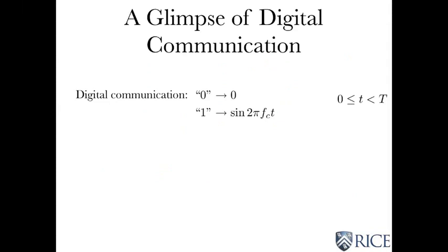Let's explore the frequency domain in another case of digital communications. I want to tell you how digital communication works. We're going to explore this in much more detail later. So here's the idea. I want to send a bit, either a 0 or 1, to the sink, to the receiver. And one way of doing it is either to send nothing over an interval of length T to represent a 0, or you send a sine wave to represent a 1.